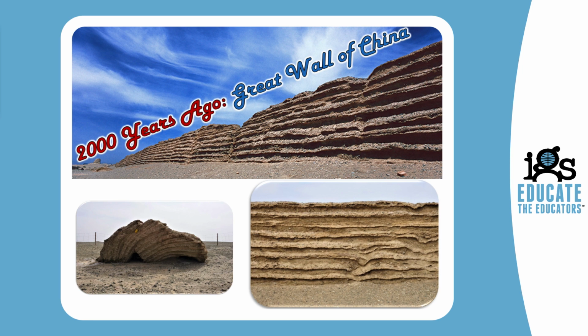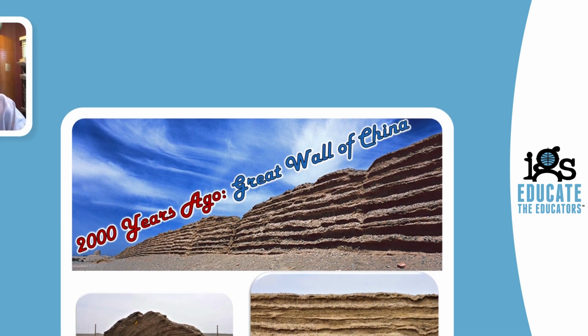This system constitutes what today we would call a geosynthetic reinforced soil system, but they used natural geotextiles at the time. Now, we may have forgotten the concept of reinforced soil systems, even though it was very nicely used over 2,000 years ago. And we reinvented it in the 1960s. We started using this concept of soil reinforcement with steel strips. Now, around that time, actually in the 1950s, is when a revolution in material science started occurring. And this is the advent of polymers. Actually, what we call today high-density polyethylene was registered in the 1950s.